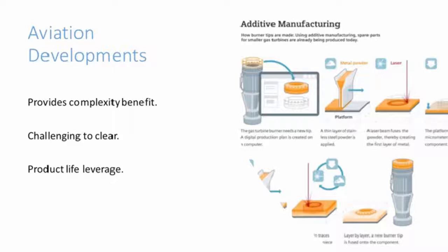In the long run, further work is likely to be completed to allow ALM in metal to be used to produce some of the primary and secondary structure of the aircraft. Here, the weight-saving properties offered by ALM will be enormously beneficial to aircraft manufacturers and operators. The necessarily intensive clearance process requires a body of evidence. A product made by means of ALM manufacturing could cost 10 times as much as a conventional item, but would represent good value if it consistently reduced fuel consumption by 1% during the component's entire service life. The challenge for the next 3 to 5 years will be to identify the components for which this equation is valid.